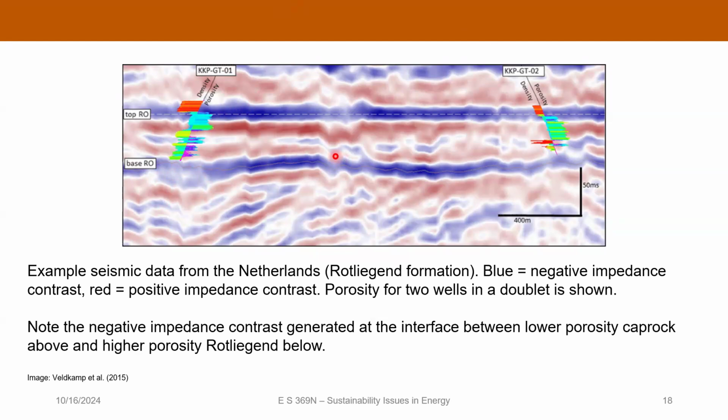Now, that's not to say that you can't deplete the thermal state of the subsurface if you pump too rapidly or you have too many wells. There is this concept they call thermal recovery, which is that after a certain amount of time, the region around the well, particularly where you're injecting the cold water, will eventually cool down, because that water needs to flow through the subsurface, and the temperature pulse needs to dissipate.